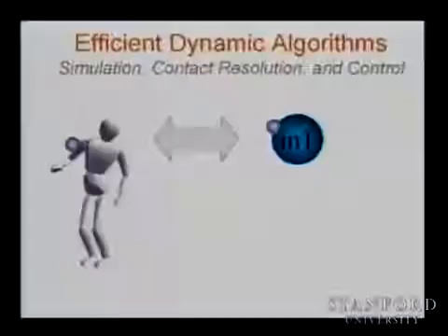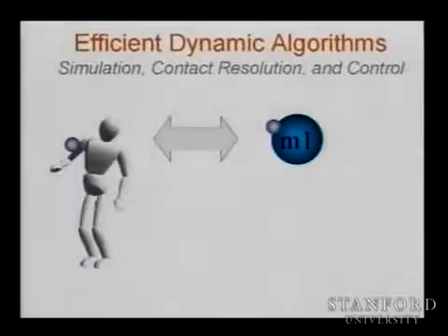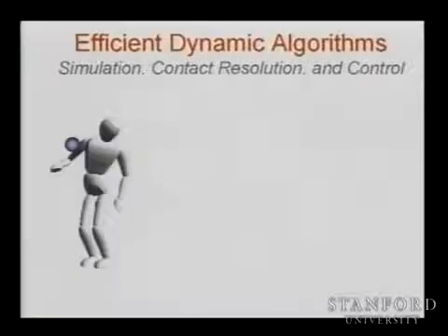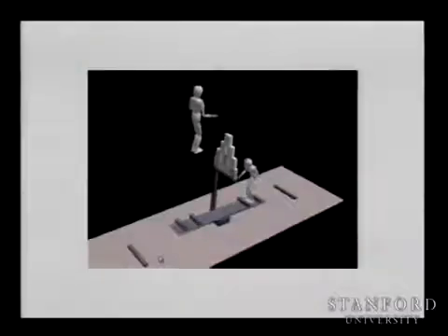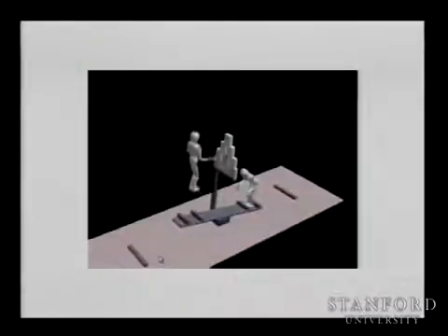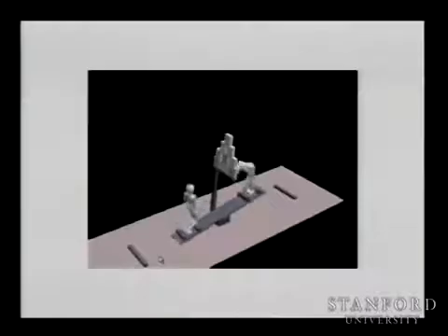But here, we are going to be able to reduce the problem to this, because we can use the mass matrix in this direction. We can use the effective inertia directly. The collision doesn't care about what humanoid robot you have. You just need to know what mass properties you have at the contact. So with this, we have a very effective algorithm that allows us to simulate and resolve collision in real time.